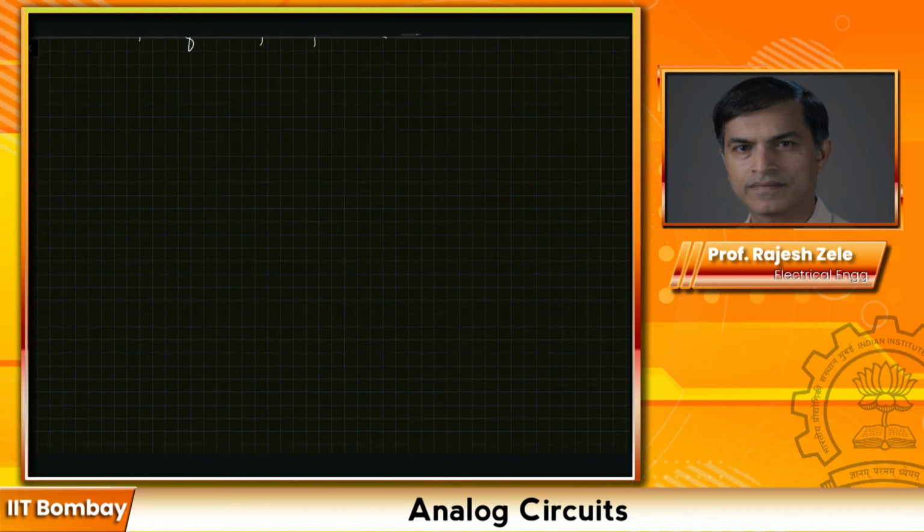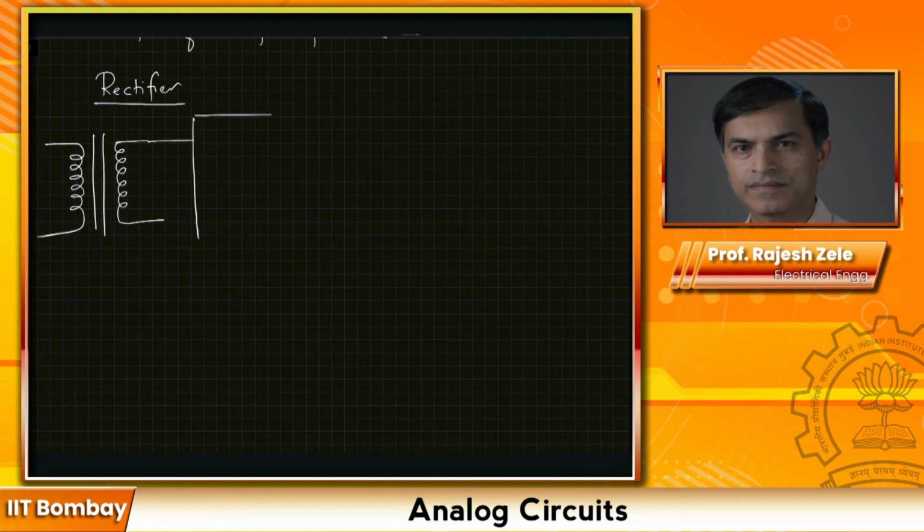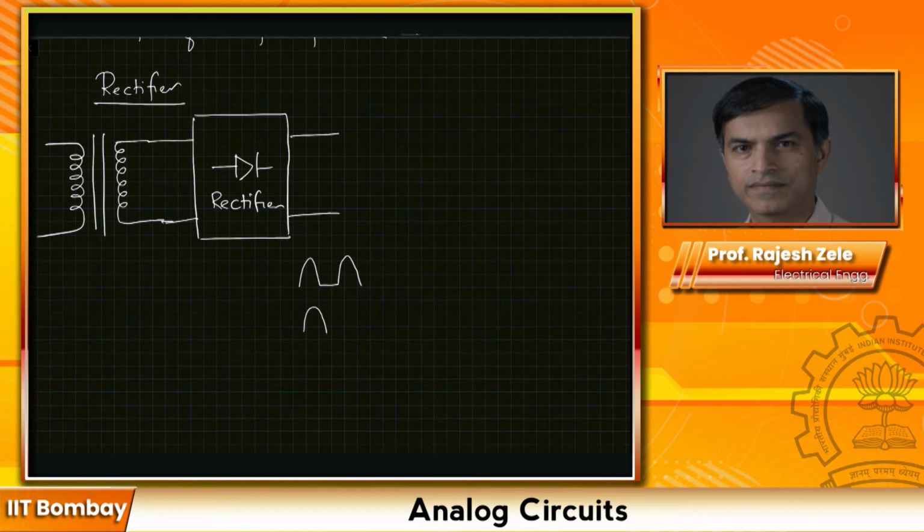charger circuit. Let's draw. So here is our rectifier, something like this. I'm just putting it in a box as whatever choice of rectifier we use. At the output of the rectifier, we have this waveform which is going in only one direction. So it could be either like this, or it could be something like this. This is your half wave and this is your full wave.